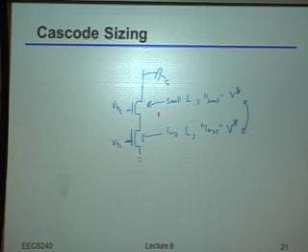Yeah, it's a good question. Doesn't necessarily mean minimum, right? You mean by V star here or channel length? Oh yeah, it very much depends on the technology. Indeed, sometimes you'll bump that ever so slightly above minimum, simply because the RO will improve much faster than the parasitics will. That's also a very common choice.